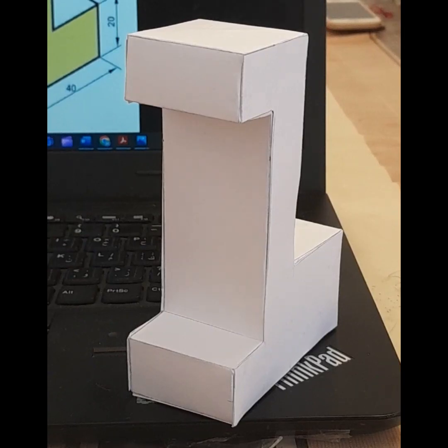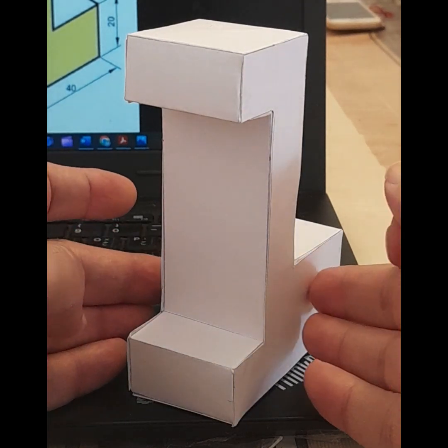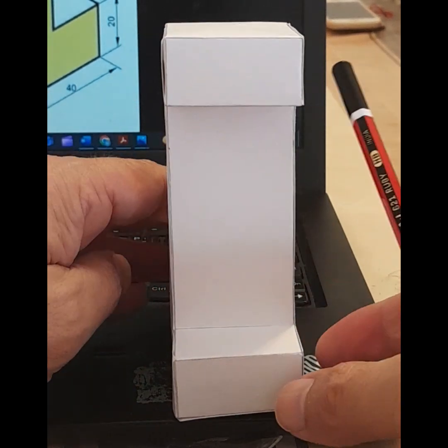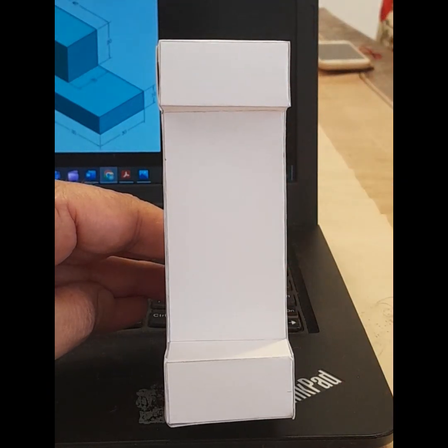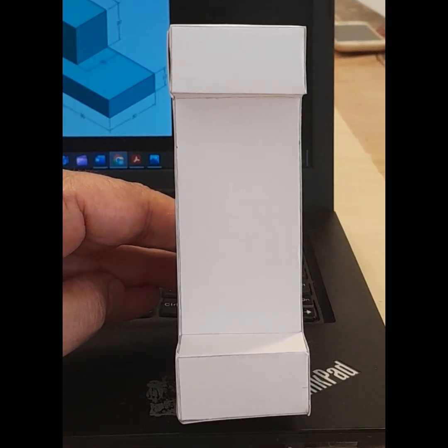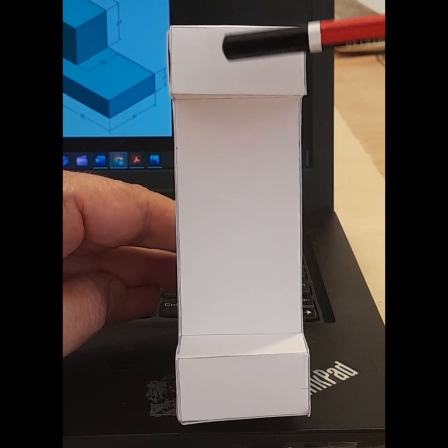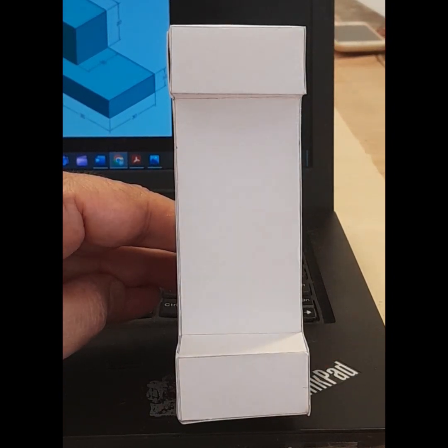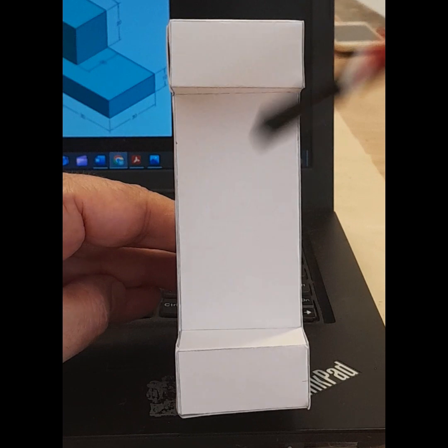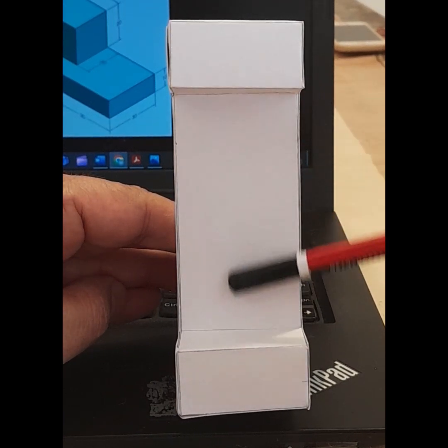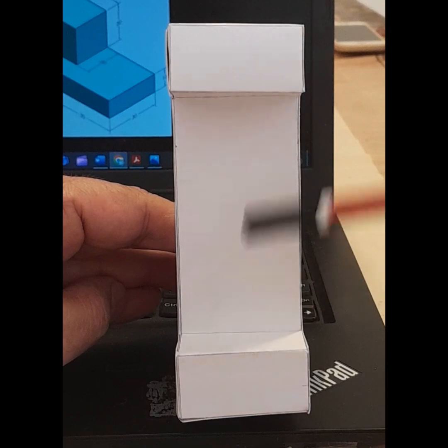After finishing the front and top view, let us now make the left side view. The left side view is to look at the part from this direction, like this. Our side should be perpendicular to this surface, all vertical surface. So what we see is three rectangles, two similar, one at the top and one at the bottom, with the full width of the side view, which is 20 millimeter. Their height, we will check on the drawing. And at the middle, the remaining of the view, or this big rectangle.